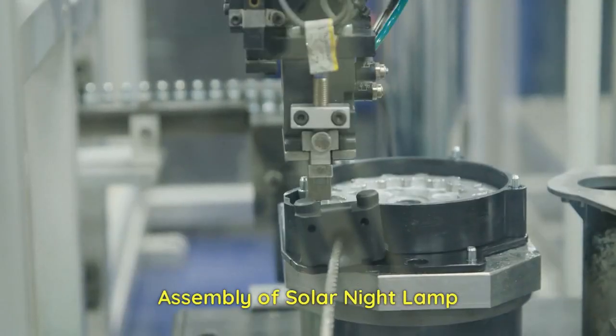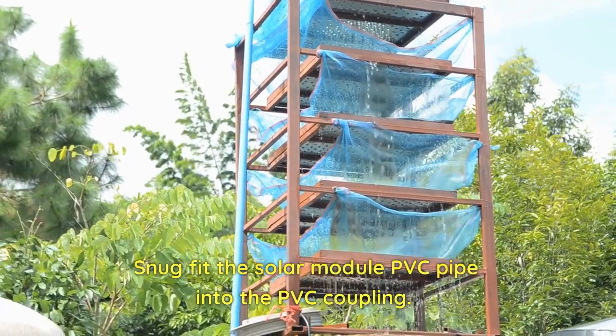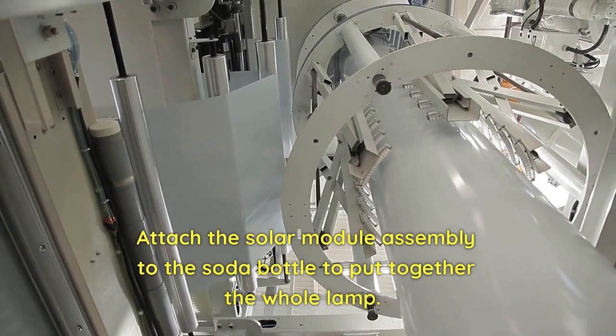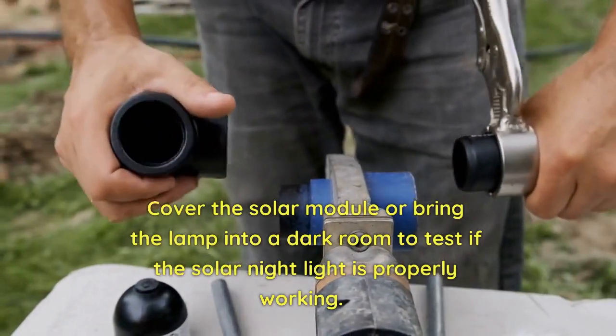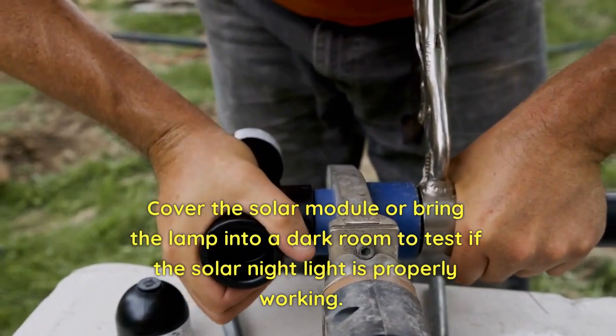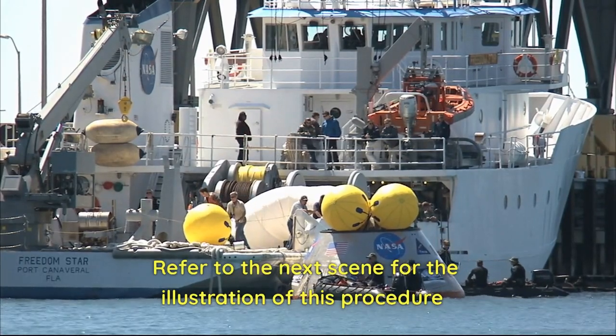Assembly of solar night lamp. Snug fit the solar module PVC pipe into the PVC coupling. Attach the solar module assembly to the soda bottle to put together the whole lamp. Cover the solar module or bring the lamp into a dark room to test if the solar night light is properly working. Refer to the next scene for the illustration of this procedure.